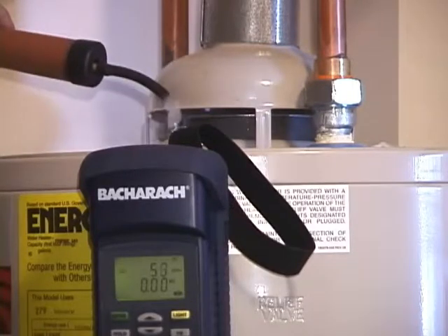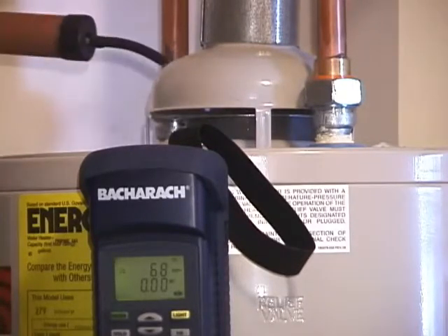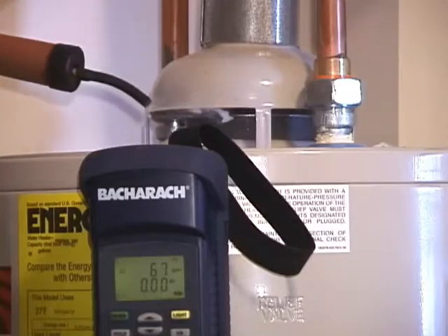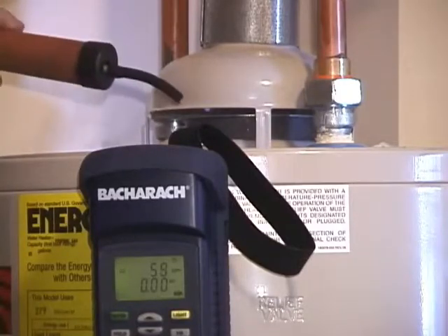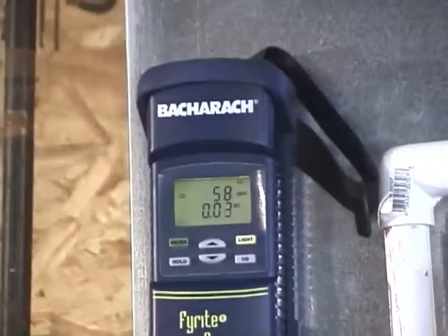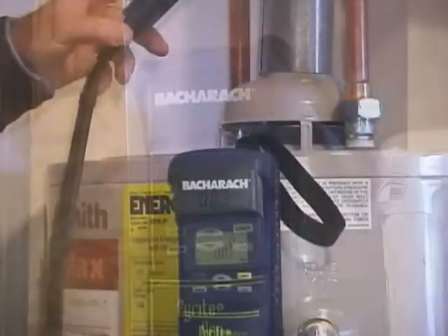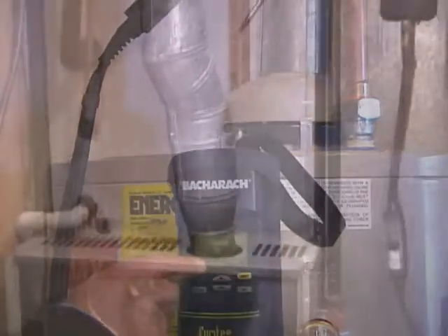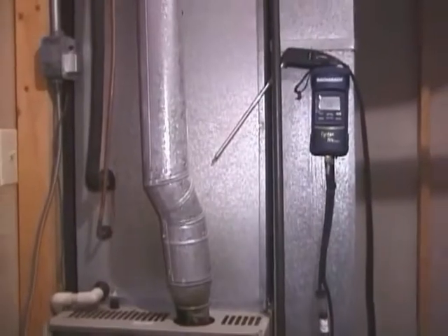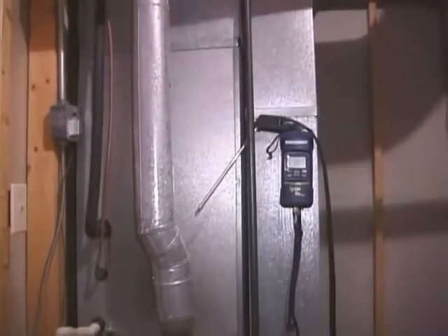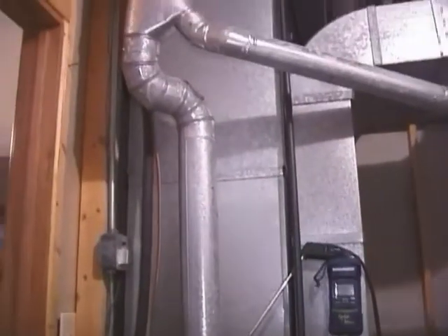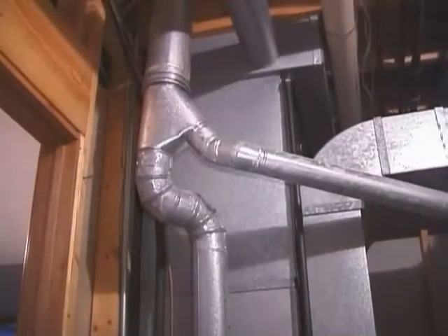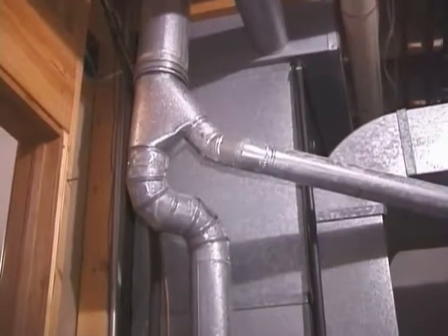That means the combustion byproducts of both the furnace and water heater spill into the home for a short period of time until good draft is established. In this example, it took approximately 4 minutes after the furnace fired until the spillage stopped and good draft was established. Although this type of common vented situation can be code compliant, as we saw in the first of our 2 examples, it does not mean it will not potentially spill combustion byproducts into the space surrounding the water heater.